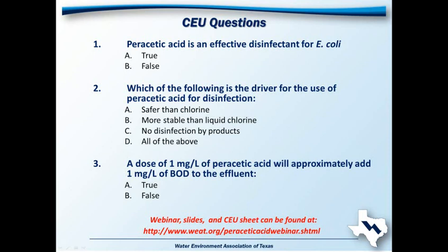Right, and in actual practice, since we do have the 2 channels, we often only operate on one channel, and it's just really flow rate driven. Because if the flow rate gets above a certain amount, we'll open the new channel, and that keeps our contact time down to less than 15, 10 to 15 minutes on a normal flow.